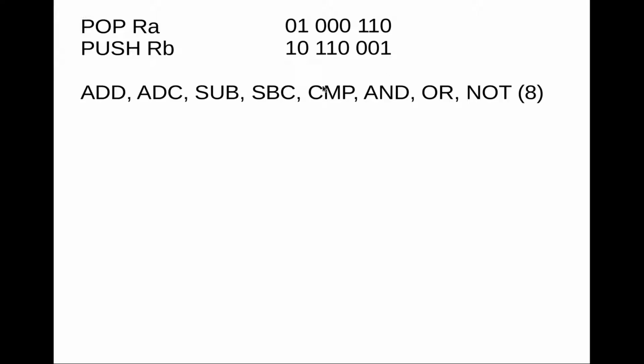Now the question comes, how are we going to encode these actual ALU instructions, which will in a way be pure ALU instructions. They won't have any effect on memory. They'll simply take two register values, perform an arithmetic or a logical calculation, and write the result back in a register. So memory is not involved at all in any of the instructions.